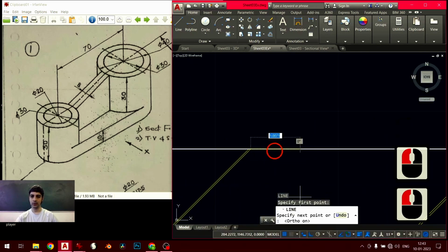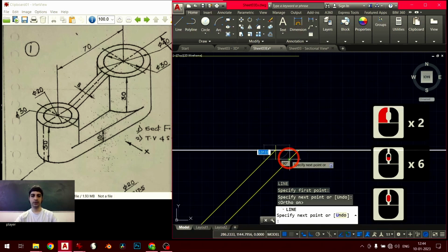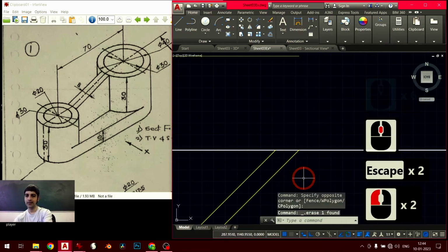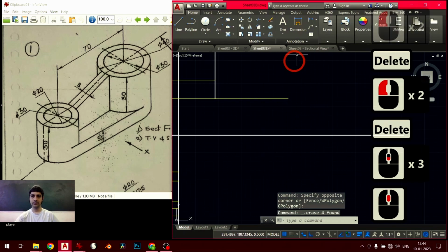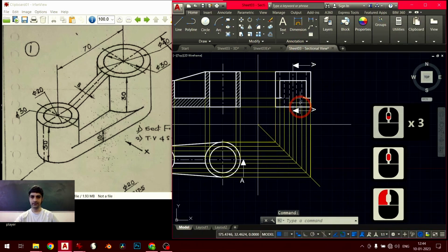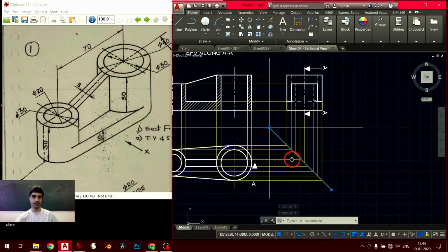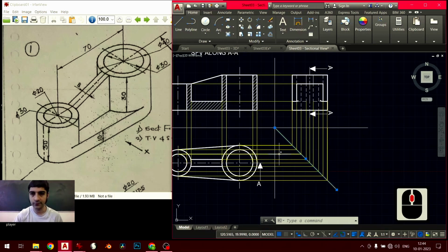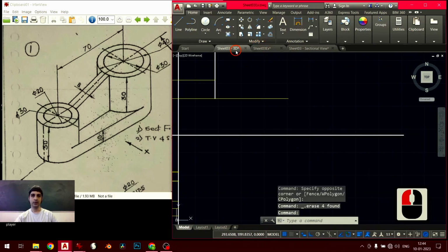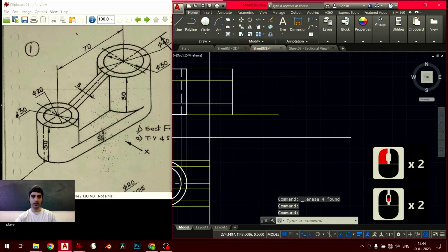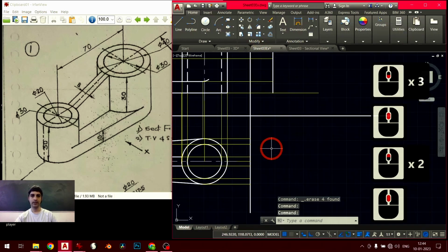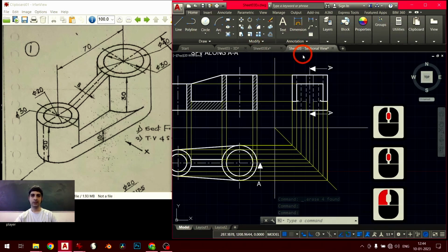I can turn ortho back on, right? And so on and so forth. And then there's the method that I prefer using, which involves these lines, right? I'm projecting horizontally to a 45-degree line and then vertically upwards. I tend to prefer that because that used to be the old method of projection of orthographic projections, nothing else. Most courses recommend that you go with the arcs method. You can use whatever you like, whatever your course prescribes. Right? So that's how you project.